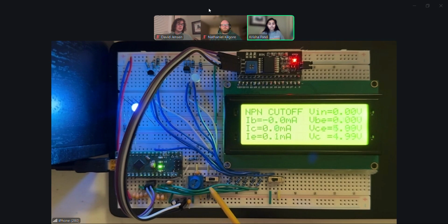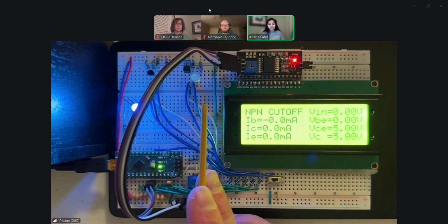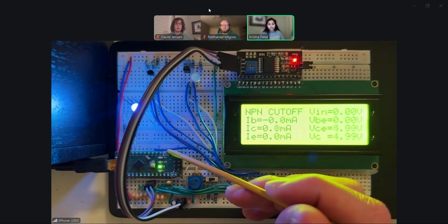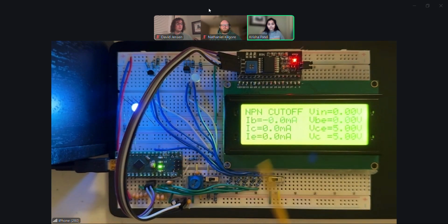The other location is this switch here. It feeds one pole of the switch, and depending on the position of the switch, it will feed either the NPN branch or the PNP branch. Moving down here, we have power and ground supplying this switch, and depending on the position, it will send a very clean high or low signal to our digital input, and that will be responsible for changing the displayed region there.